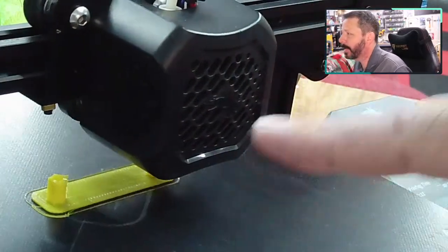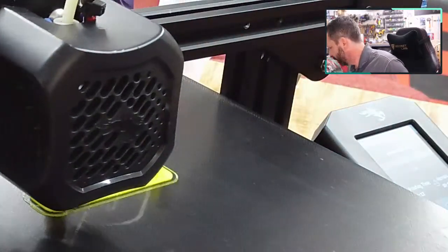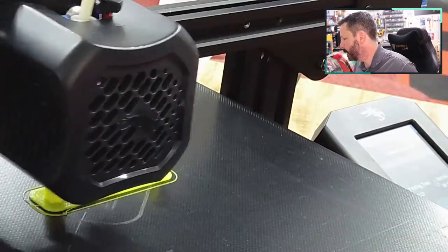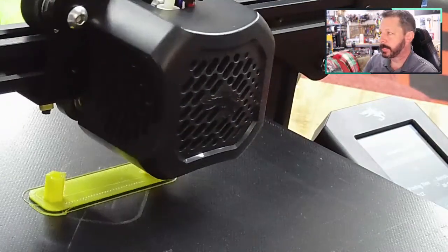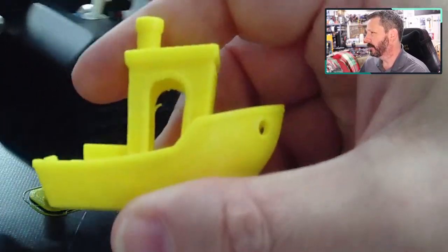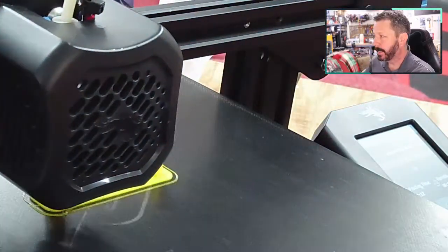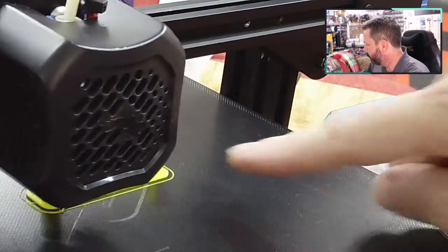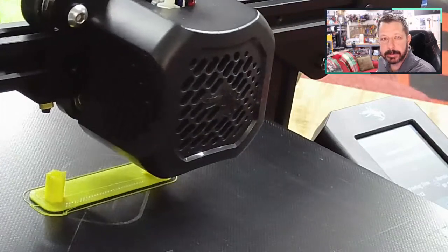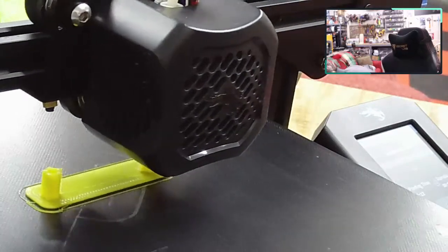You can't even see them on the camera, but there are some super thin wisps between these, and that's my 5mm retraction, which I already saw had issues inside the cabin of my Benchy at that same setting. So I expect that, and I can see them. Hopefully when it gets to some of the higher amounts of retraction, those wisps go away.